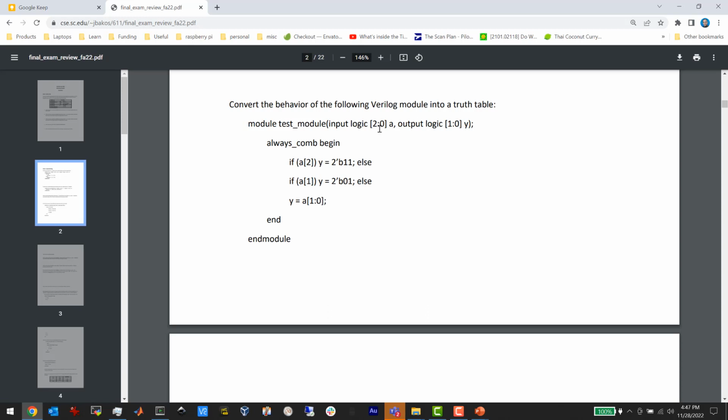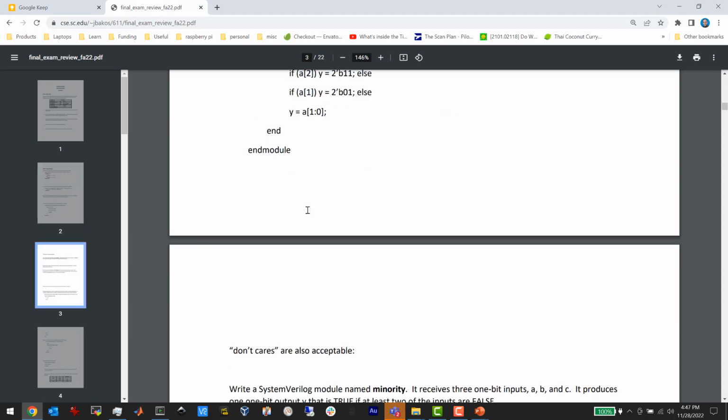So the truth table will have 8 rows, but because of that if statement, that means that 4 of those rows are automatically going to have an output of 1, 1. Right? Just because we look at the first bit, and that covers 4 rows of the truth table. And then, of course, you have to deal with the other 4 rows below.